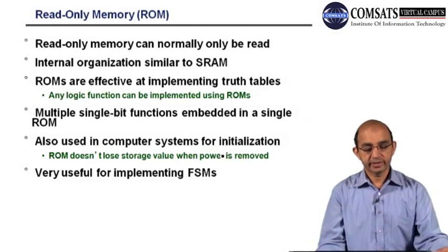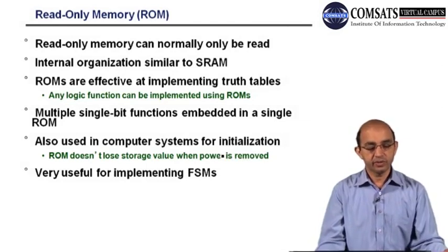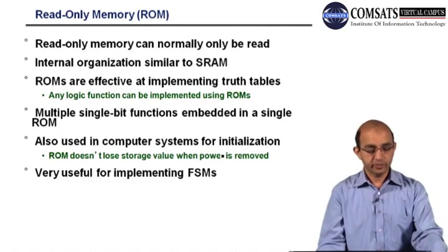Then we moved to ROM. Normally this is considered as read-only memory. But we talked about certain mechanisms that are used in order to write onto the ROMs. But we have to take care, because there can be some serious problems whenever we have power outages or problems like that. The internal structure of the ROM is similar to the SRAM.